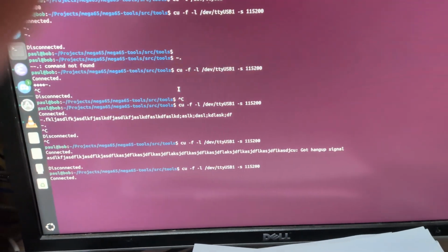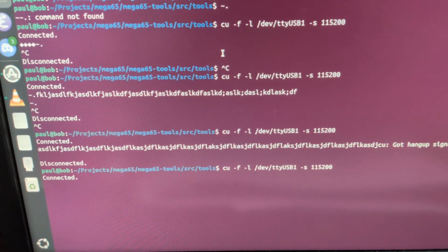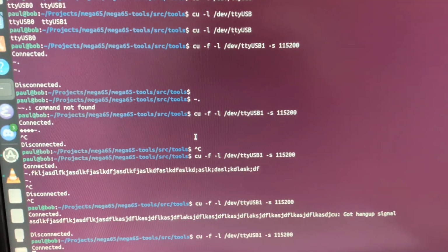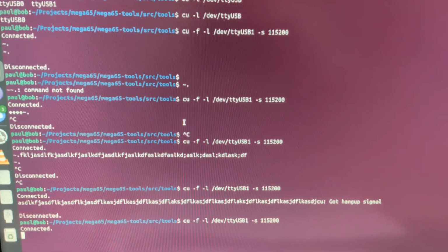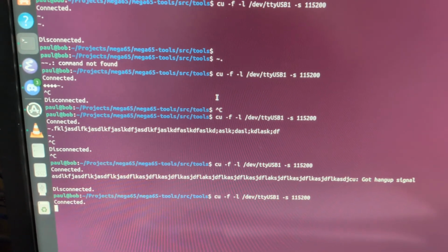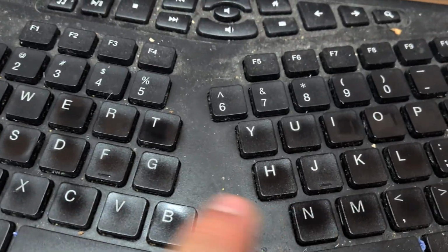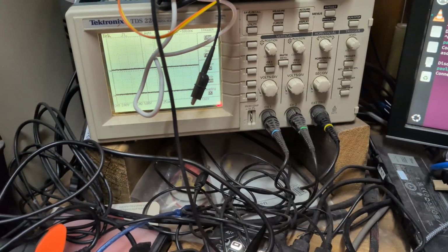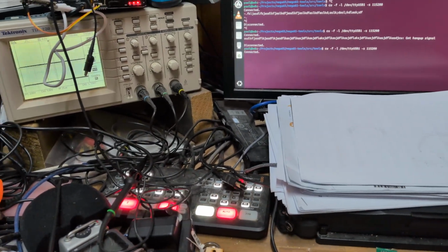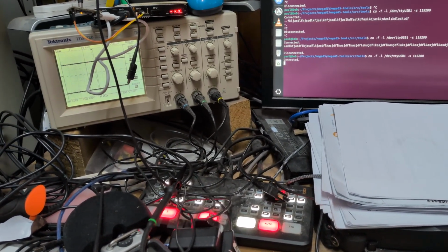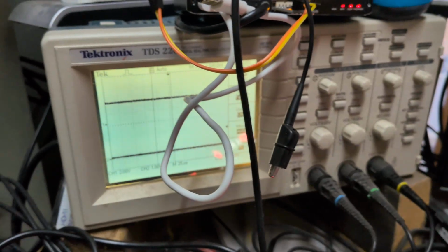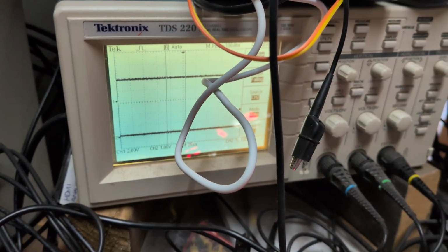Now this is where it gets a little bit fun. So this is talking to that other UART interface. So I can, on my keyboard, pretend to be the modem making a phone call. So if I start typing R-I-N, and I won't press G just yet, because when I press G, we should actually see the power go on, because the low power FPGA has detected that the modem needs to do something.